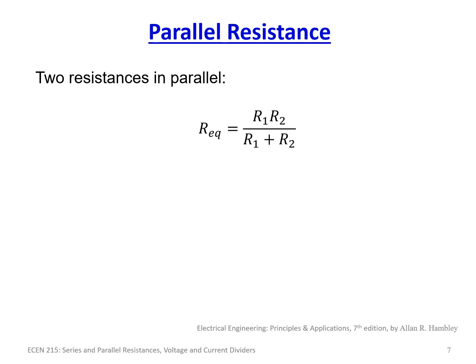So for two resistances in parallel, there's just this easy little formula to remember. And you can actually use this formula for combining pairs of resistors. So if you have three, you can take two, use this equation, and then take that equivalent and use it with a third. You can just keep chaining these together in groups of two.